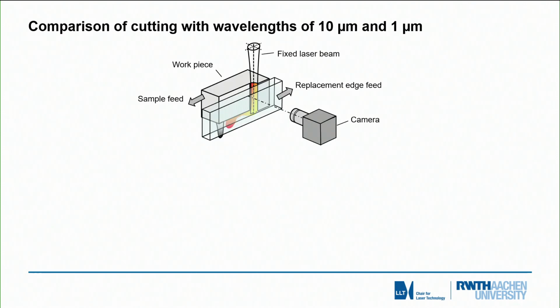In order to make these effects visible, we designed a process which we called trim cut. So what we do is we take a cutting edge and we just cut and trim the edge of that piece of metal. On the other side, where actually there's no workpiece, we place a piece of glass through which we of course can look and observe the process with a camera. In doing so, we get the simulation of a cutting curve quite close to reality, and in parallel have the ability to look into the cutting curve itself.